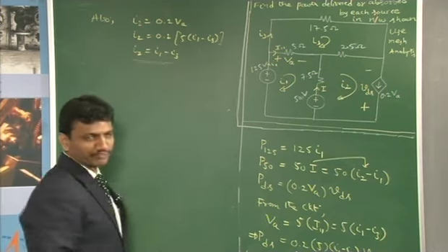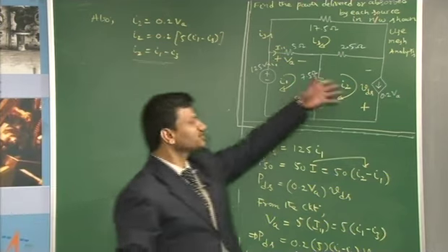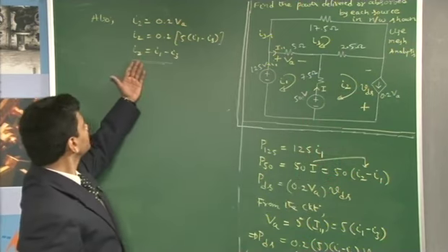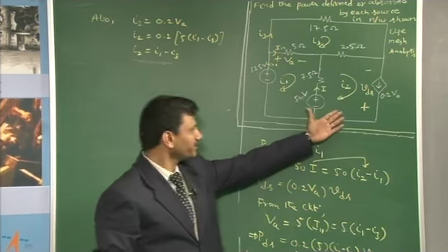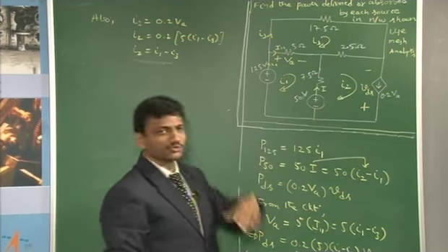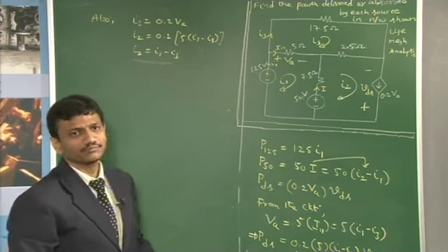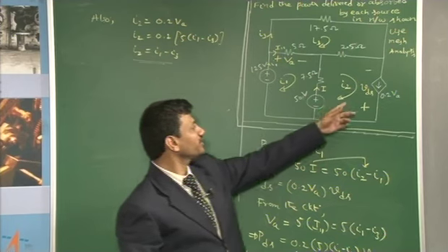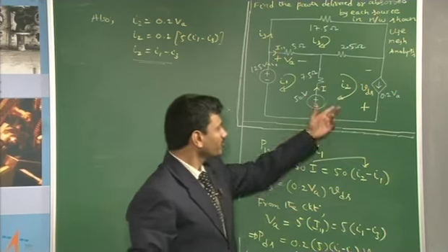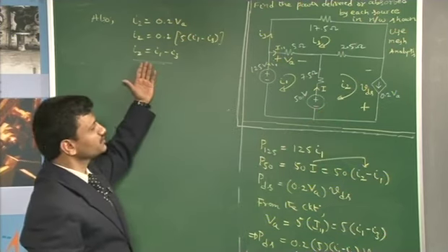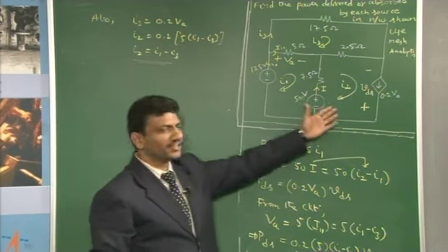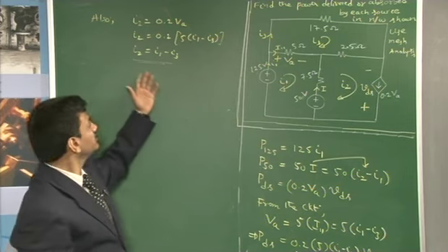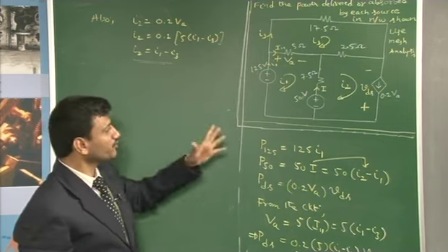Now what we have to remember is, we apply KVL to each of the meshes to get an equation, and now we got an equation related to I2, or related to mesh 2, already. So let me tell you that we need not again specifically apply KVL to this particular mesh. Why? Because we already have an equation associated with that. Even if you apply KVL, it would be redundant. That means without that also we will be able to find the values of the mesh currents. This is what you have to remember.